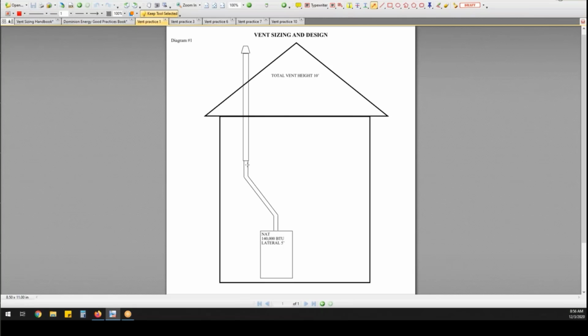In this case, it's a piece of pipe, 45, a piece of pipe, 45, and another pipe. And then the rest is your main stack. So your connector might be a 12-inch piece of pipe, and then the rest is your main stack. And in a perfect world, that's how we'd like to design them.